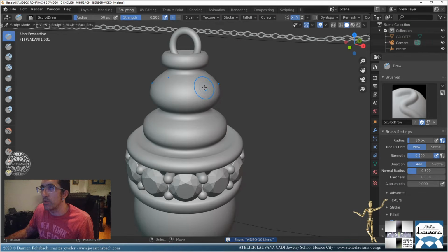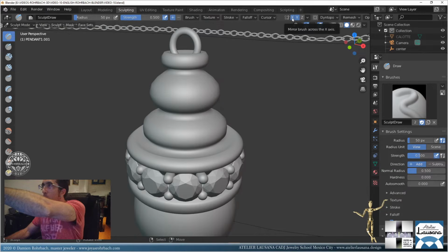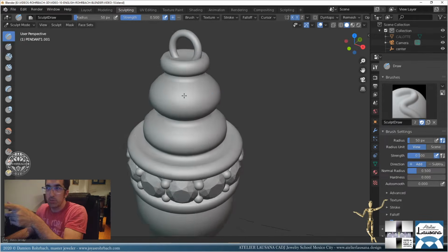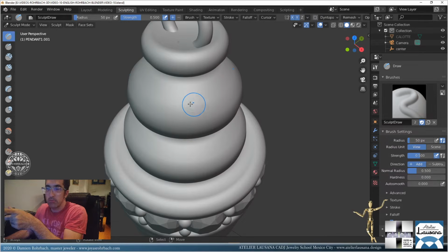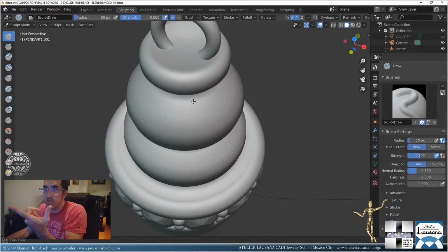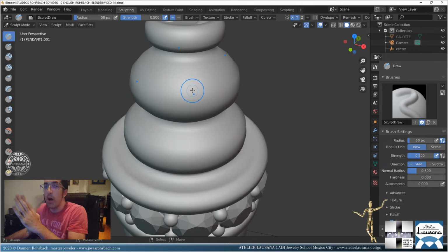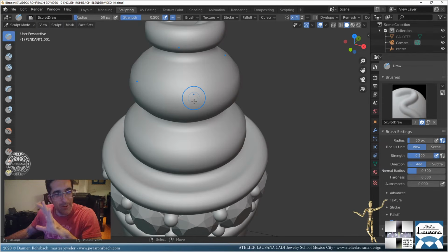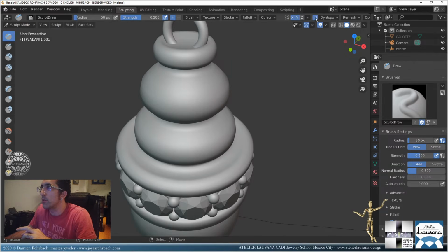Now let's go to sculpting. X and Y should be this, not up and down. That would be the Z axis. That's why, because up there, we have the X and Y mirror or symmetry turned on. So when I go to my mesh, that's the correct thing that I want to see. If I have X and Y and things are going up and down using the mirror, I know I have a problem somewhere. So just go and hit Control A and bring transformation to 0.